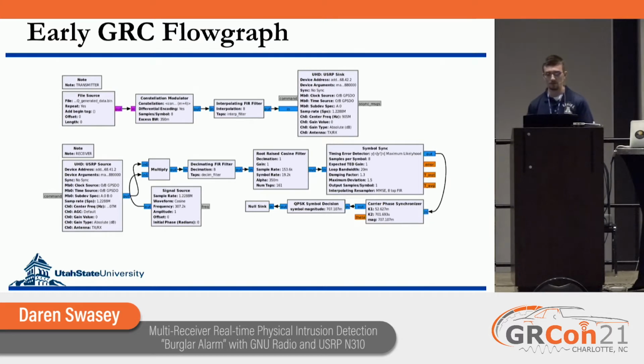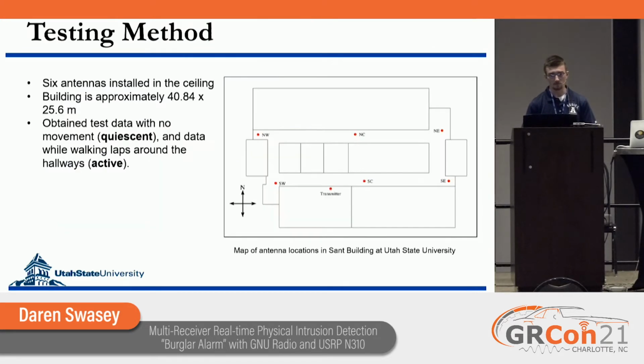The signal gets basebanded, filtered, then runs through the symbol sync and a PLL. On the receiver end, all of these outputs or inputs can be used for potential file sinks where we can evaluate that data and see if somebody was moving, if somebody was here, and whether it tells us anything about that. And it actually does. Again, I'll be showing the PLL data later.